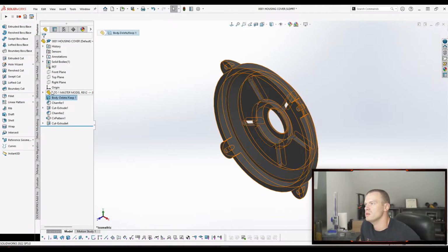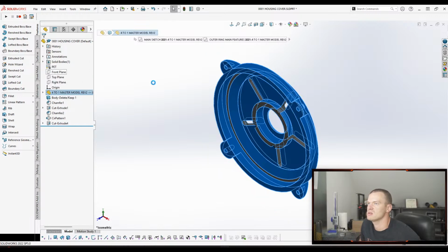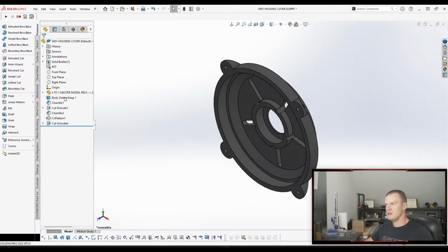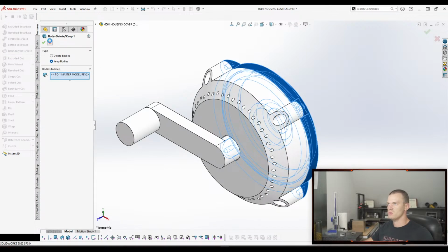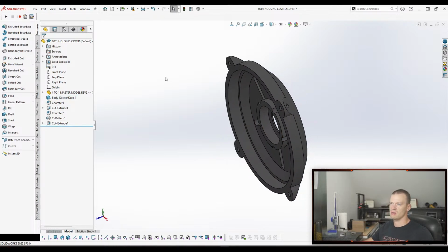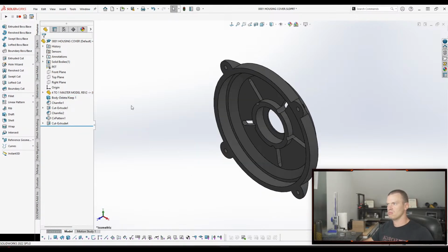So you insert this, but it remains. Yeah, so you're just inserting the part. Okay, interesting. And then you just have to delete, keep this out, right? Keep the body that you want. Yeah, cool. And then you make your minor modifications to it that don't drastically affect anything. And then you save out that part. Okay, cool. I like it. Yeah, I mean, it seems viable.